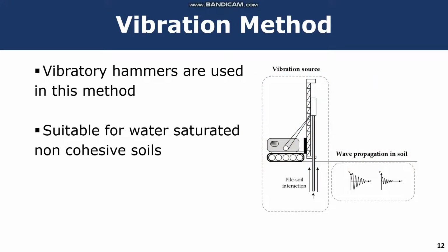In the vibration method, we utilize vibratory hammers. The vibrations basically allow the pile to penetrate easily. So it is mostly suitable for non-cohesive soil like sand.